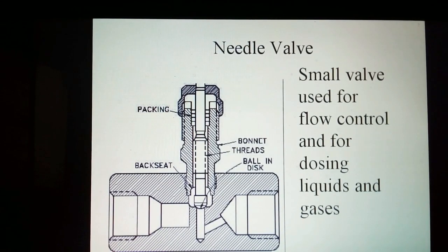Needle valve is a small valve used for flow control and for dosing liquids and gases. Resistance to flow is precisely controlled by a relatively larger seat area and the adjustment afforded by fine threading of the stem.